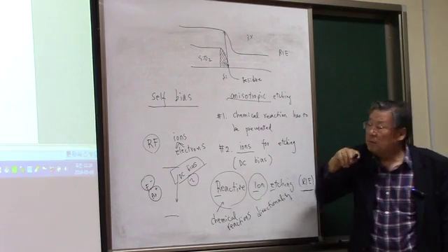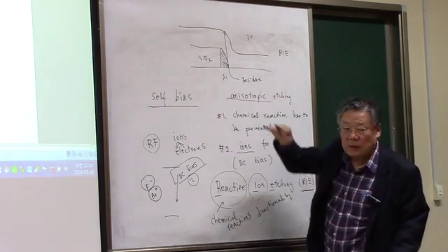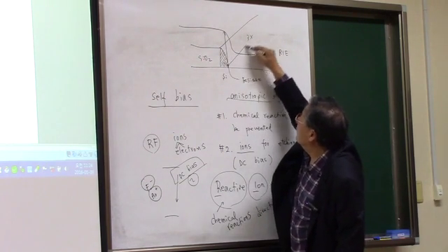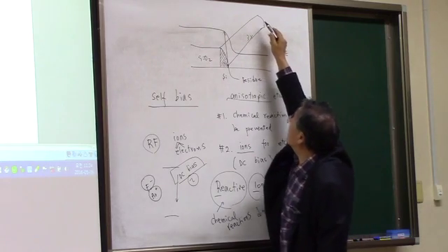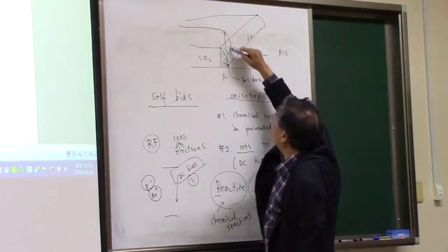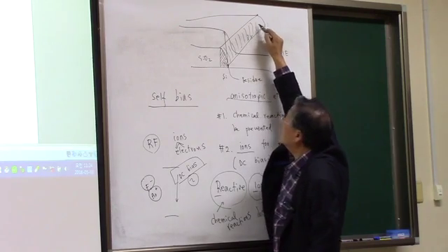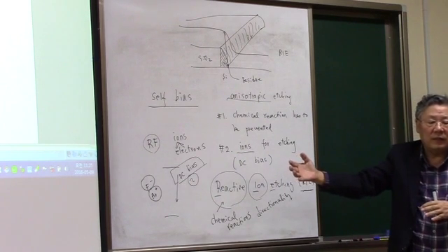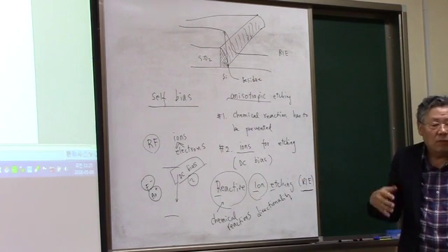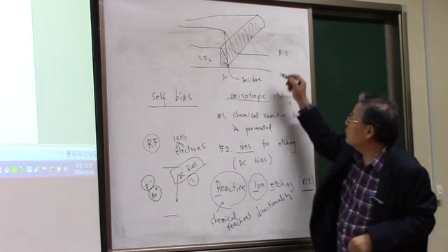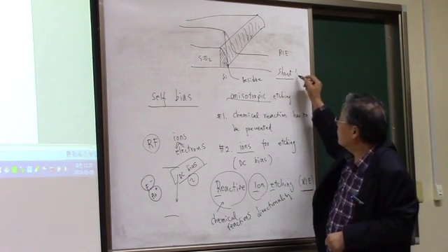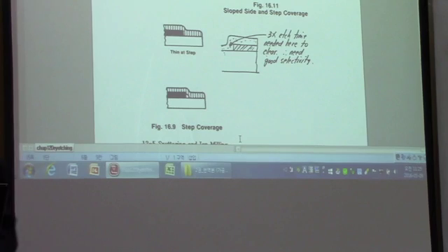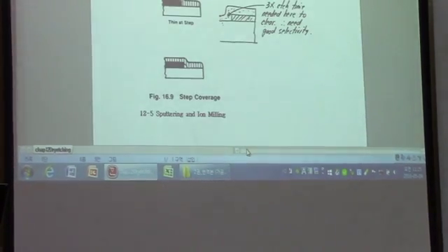Okay, and then if you think of it in a two-dimensional way, this is going to be formed something like this, okay? So this whole thing is just metal, and this may connect to the next transistors, which we call a short. Okay, this will lead to the short problem. So this residue is a kind of problem that we can have in anisotropic etching.